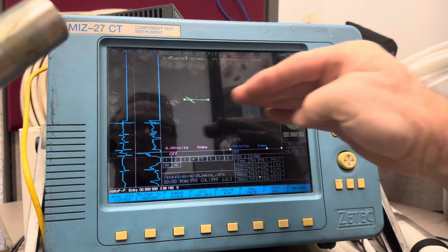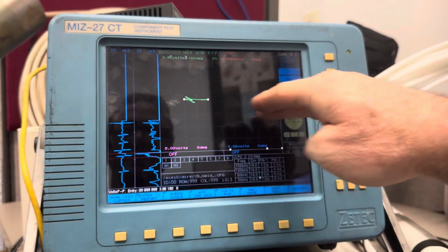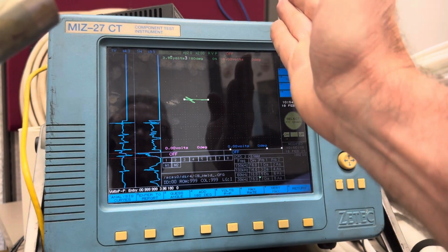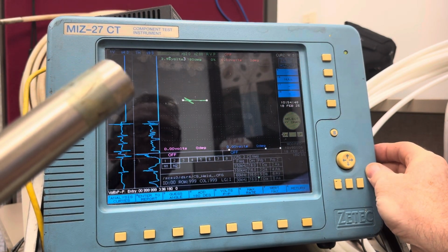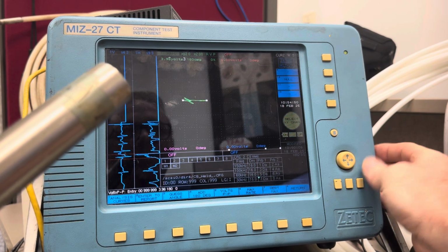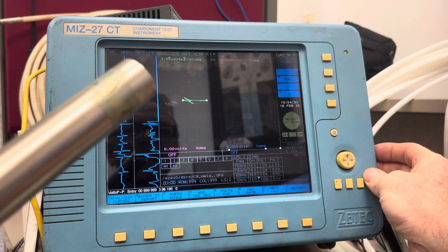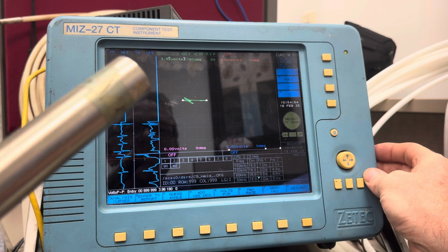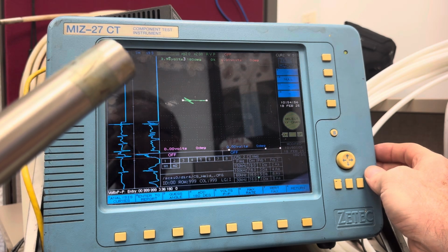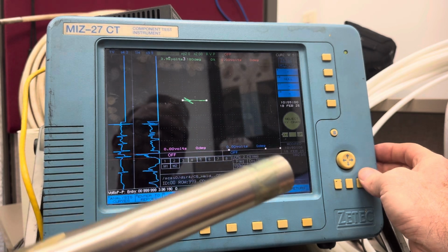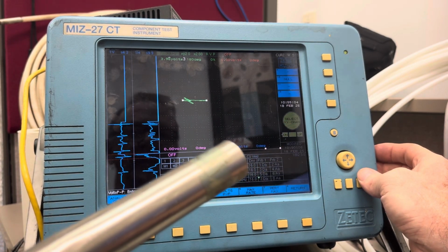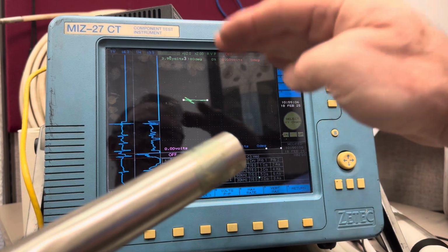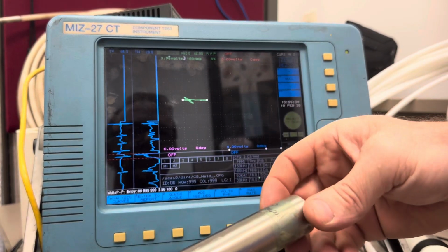Now, if you got a dent that's horizontal and it starts to rotate up as you decrease through the frequencies, we call that a distorted dent with an indication, a possible indication. And that's the case where we would probably go in with an array probe or a rotating probe to get more information on that location. Because some things will rotate up just a tiny bit. You know, every dent's a little bit different. But typically, they're not going to rotate much as you go through the frequencies.